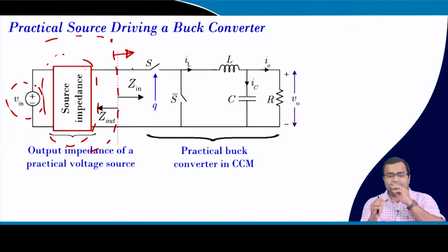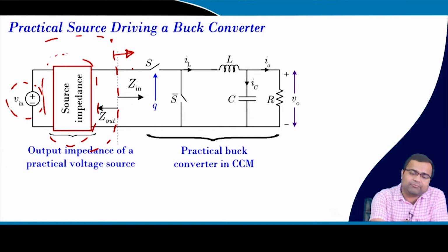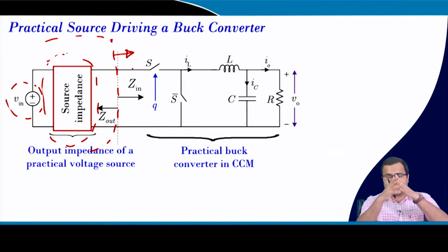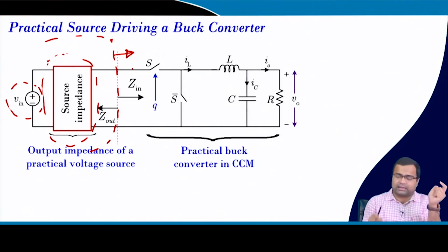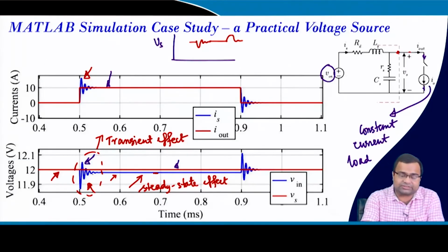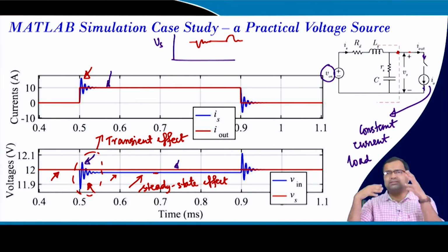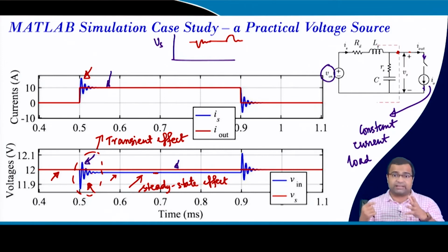That means, if you take the power of this voltage source, not all power will be around the DC value. There will be some power which will appear at the damped frequency of this transient behavior, and that power can come at very high frequency, and that is associated with the EMI effect. And if that power amplitude is large, then it can interfere with different communication devices. Okay.